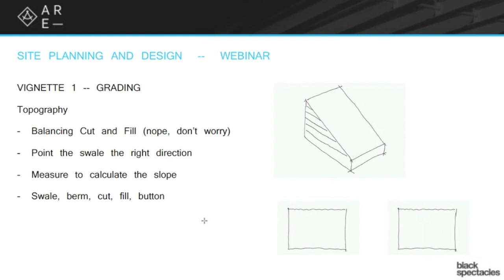One of the things you'll be shocked by is how you see those giant dump trucks, with this tiny amount of soil in those things, putting sand or gravel or anything like that. It takes 20 of those, 30 of those, 100 of those before you have any real amount of soil or gravel or whatever it is you're moving. It's very, very expensive. The scale of the stuff when you're outside is just much bigger than it naturally seems. So having 30 or 100 trucks moving in and out of your site is very expensive. So you're always trying to balance cut and fill. If you're going to take soil out, you try to find a place on the site that you can use it.